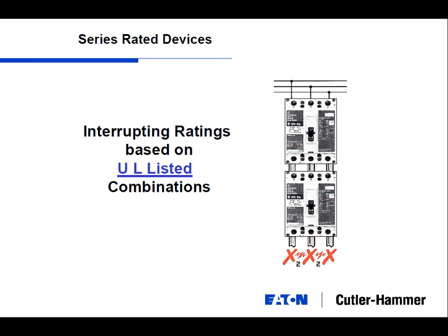Second, a fully rated system, where you've got a main and the same feeders, or higher rated feeders. There's no promise that the feeder is going to trip before the main, but a lot of the time it will, and by that I mean low-level faults.